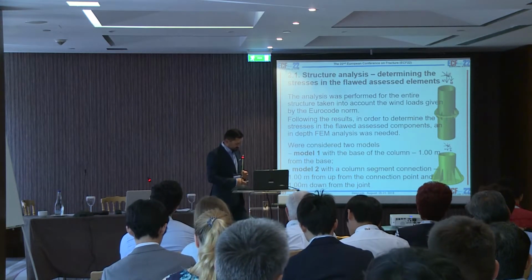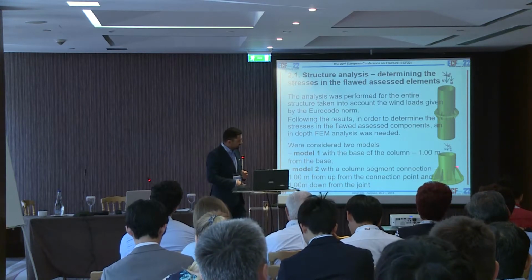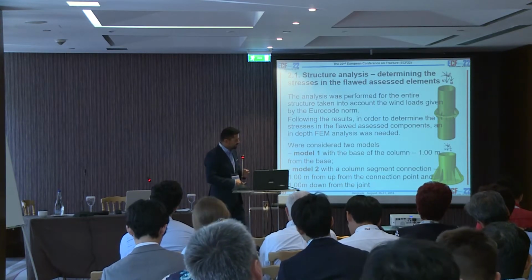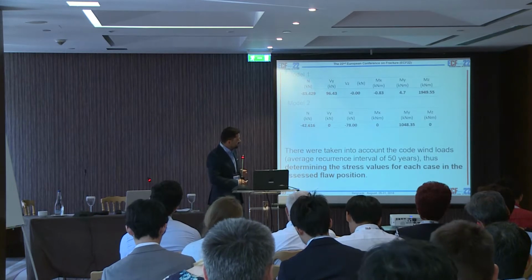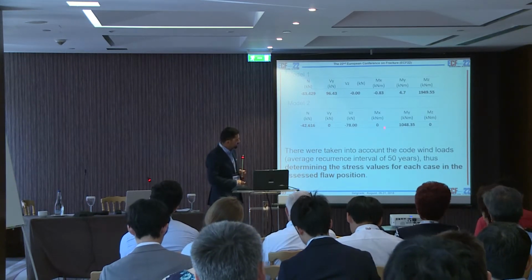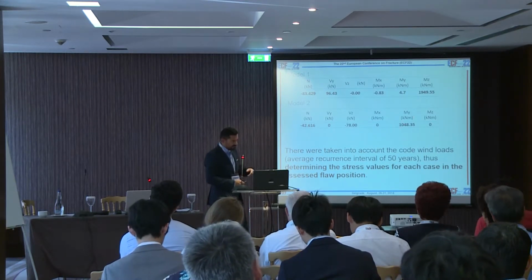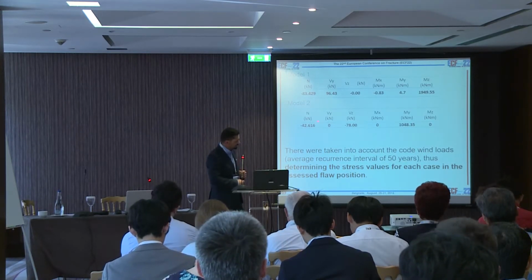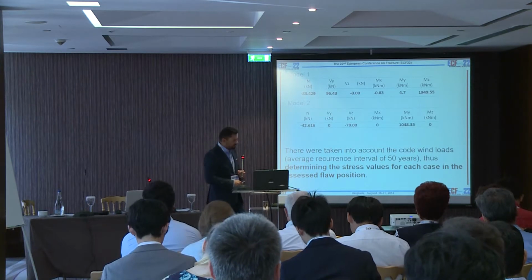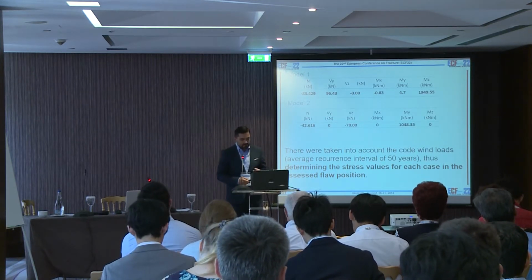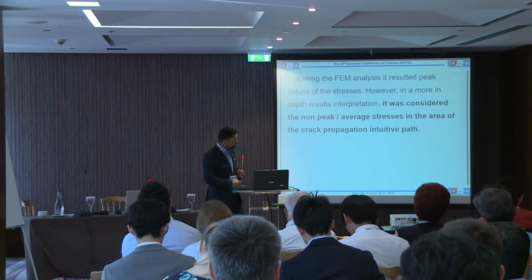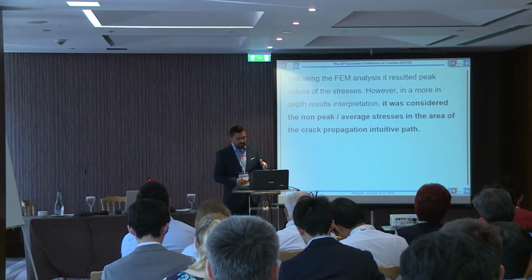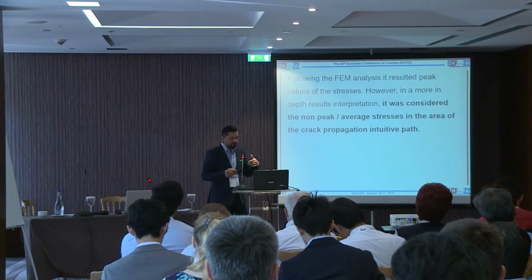I will not get into details here. It was done with the Abaqus software. Some boundary conditions were used for the forces that came from the analysis: the bending moments, of course, axial force, and shear force. In the end the stresses were determined in the areas of the possible flaws.